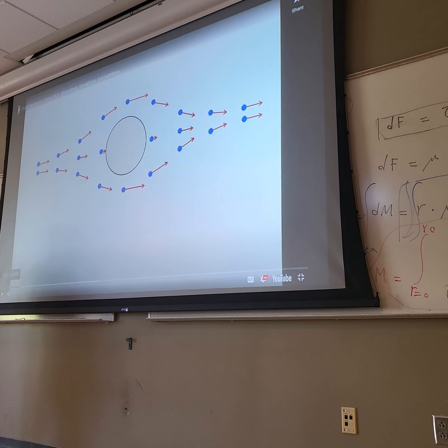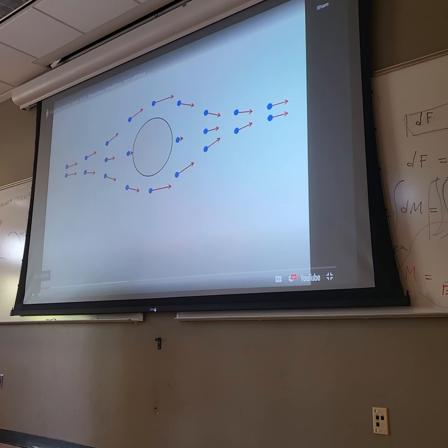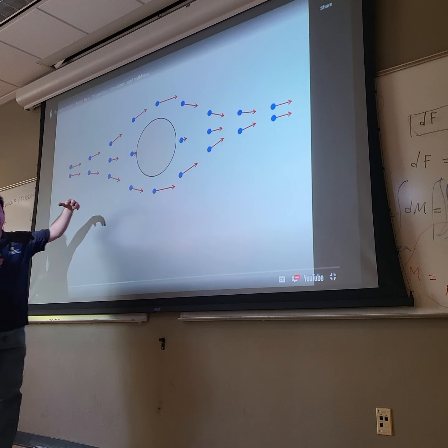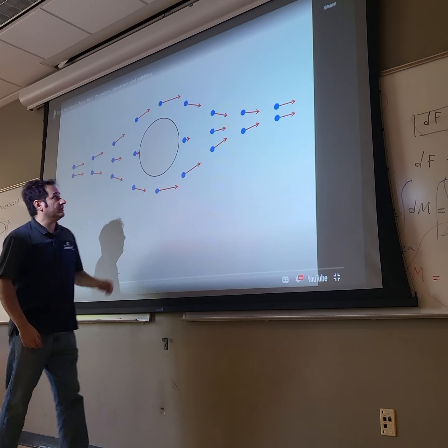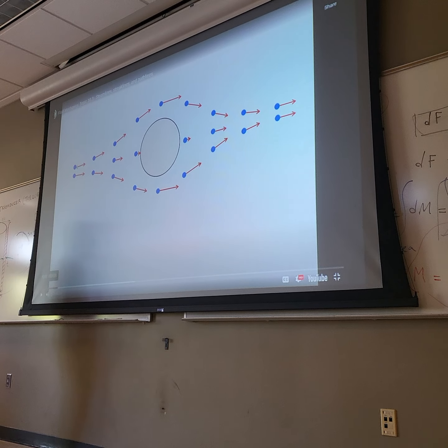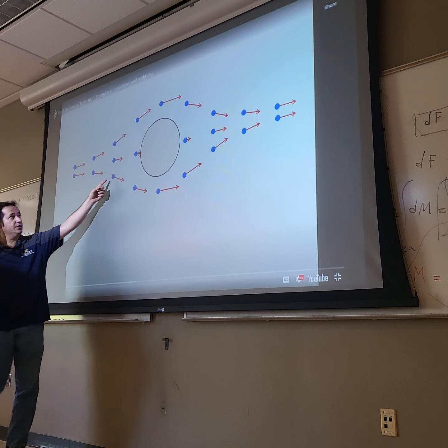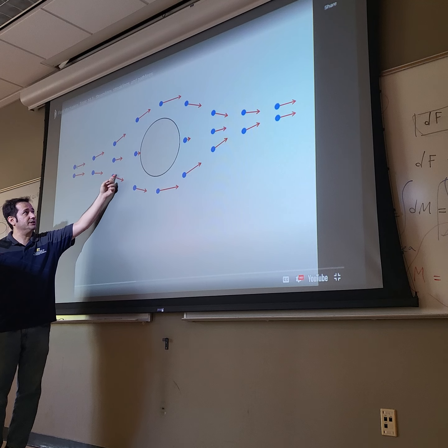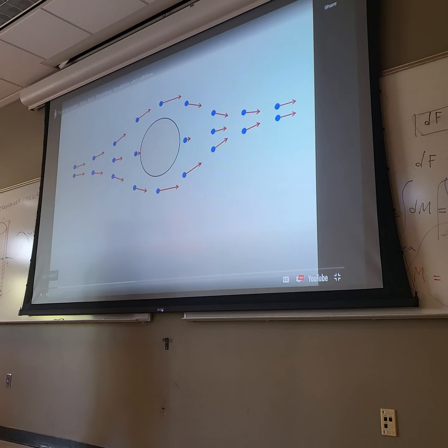It's kind of like an obstacle against the fluid flow. The fluid is going to go around it, okay? And then you have what we call the velocity field. You see, at every point, the fluid has both y velocity and x velocity. And so you get that velocity is a vector. So it's going to develop a field, and if you